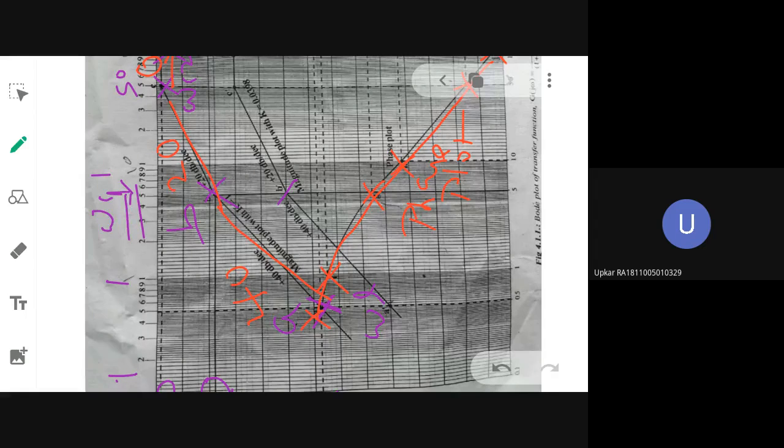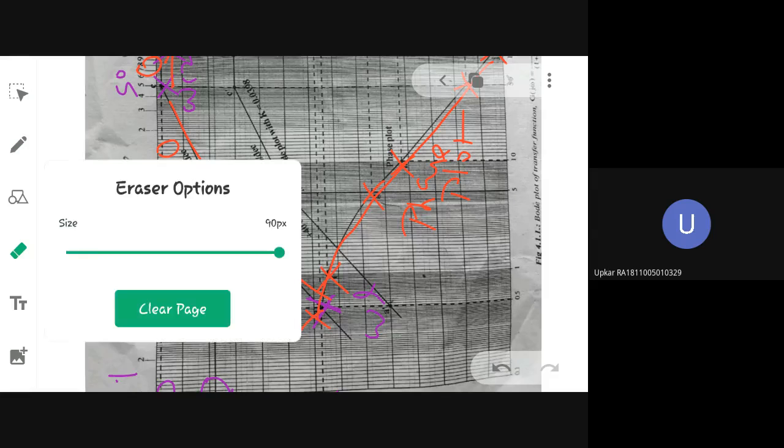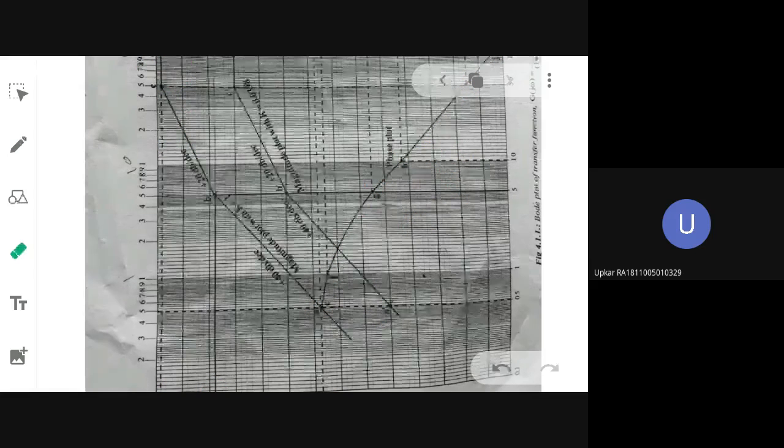Now what you need to do is find the K value. For what K value have you drawn this graph? The assumption that you have made is that K is equal to 1, and you have drawn this magnitude plot with K equal to 1. But the actual value of K you have to find for the omega GC specified in the problem. In the problem statement they have asked you to find the gain for what gain crossover frequency? 5 radians per second.